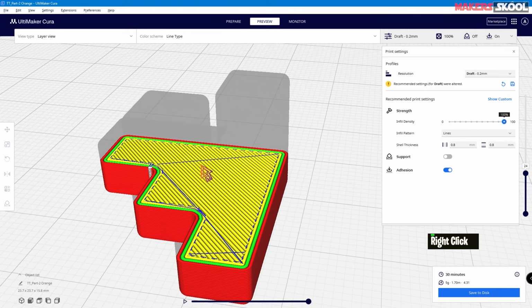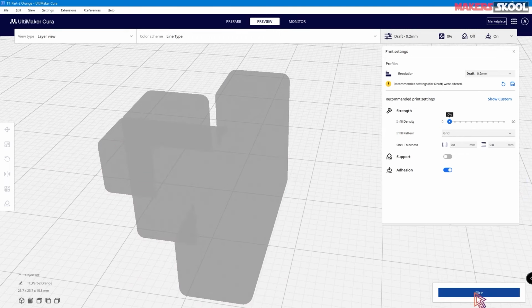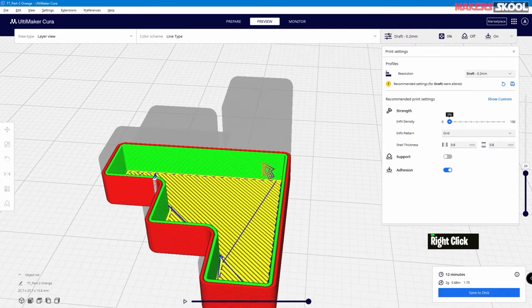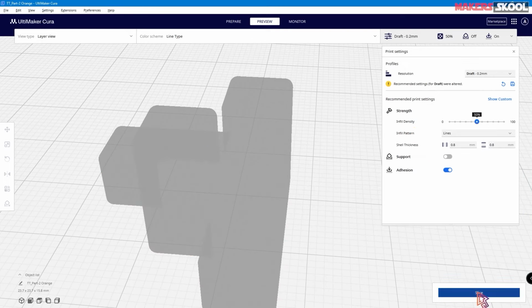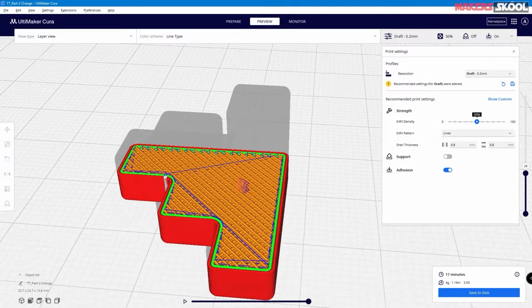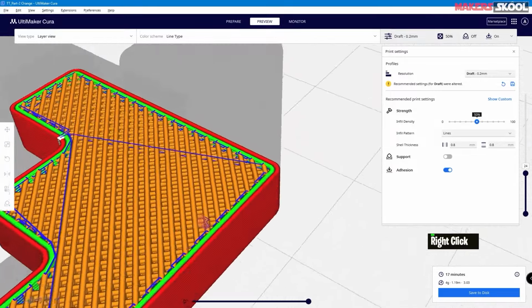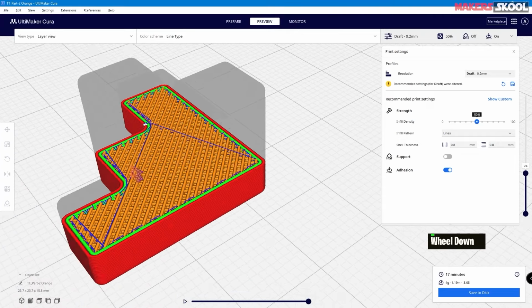Full infill density means that there is no gap between the filament patterns. It's completely filled. And similarly vice versa at 0%, when we slice it, you can see now that there are only walls around. 0% infill means no material used inside. And at 50% you'll see that there will be 50% gap and 50% material will be used.